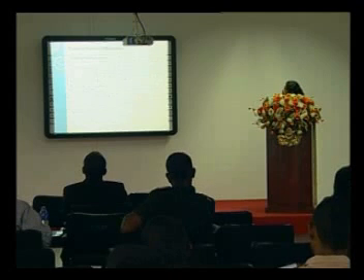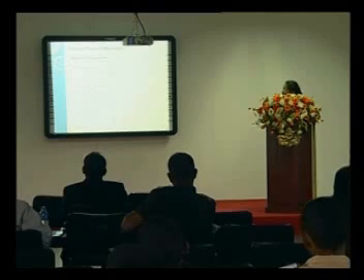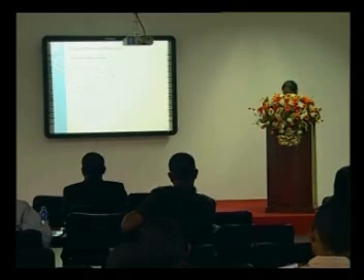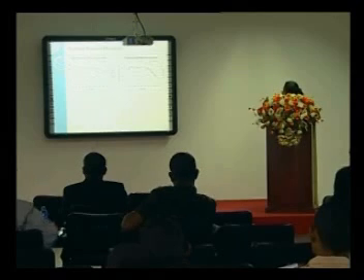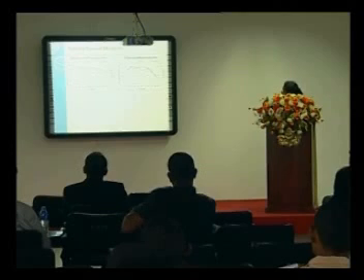This shows the removal efficiency in the vertical subsurface flow system, and the green line is for the horizontal subsurface flow system, and we can see there is slightly better removal in the vertical subsurface flow system. However, the efficiency slightly decreased with the increasing hydraulic loading rate. When we see the total suspended solids removal efficiency, up to about 20 hydraulic loading rate it slightly decreased, but then it drastically decreased since then.